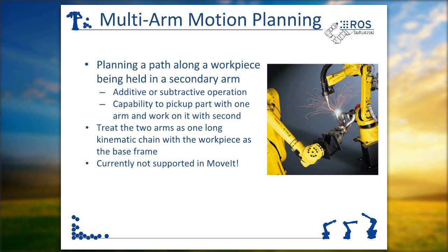And so then, if you have two 6-DOF arms, suddenly you have one 12-DOF arm, and you can get to a lot more places on it. And then we'll have to have a lot of mode switching in MoveIt on how to switch between a single arm picking up the object and then becoming a much higher degree of freedom arm.